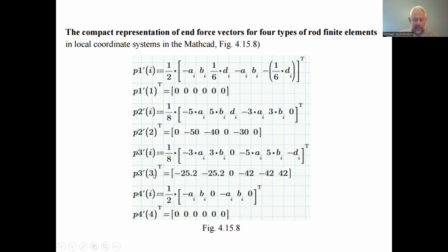We have the inclined finite element of the length of 5 meters. So we have this one, the hinge connection to other finite elements we have here. So the bending moment, the third end force is equal to 0. This is the support embedding equal to 42. The moment. This is the fourth finite element, vertical stand, all zeros.